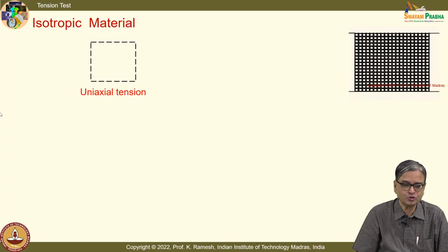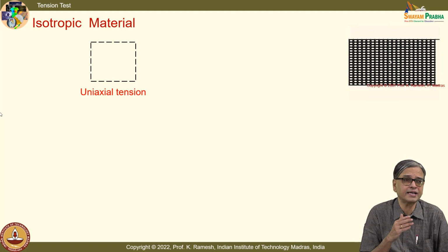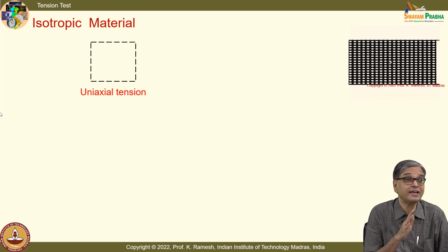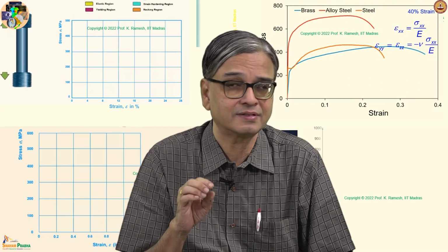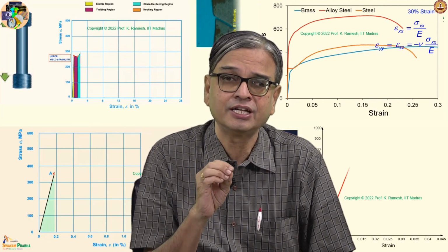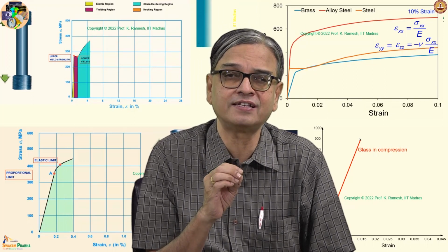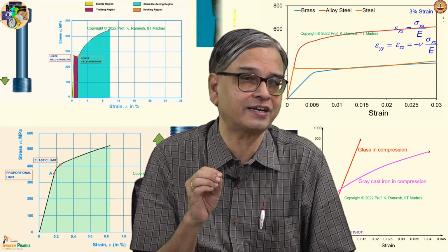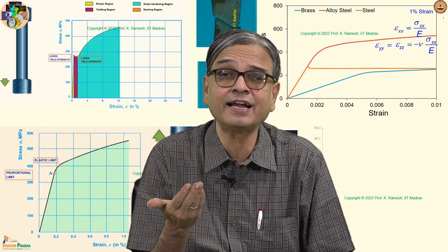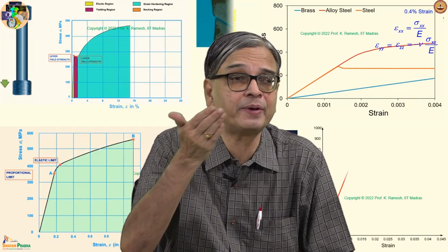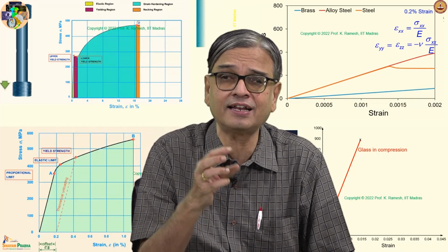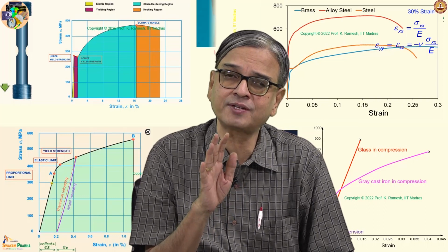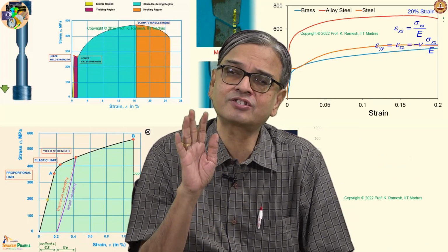And you should also look at this: all the time when we discussed state of stress and state of strain, they were developed independent of the material. For the purpose of discussion, I brought in how a chalk fails, it's a brittle material. For the illustration, how the ductile material behaves differently, so that you appreciate why I should collect the information on all the possible planes passing through the point of interest. To illustrate that, I have taken advantage of failure of some of these materials. Otherwise, the concept of stress stands alone, the concept of strain stands alone.